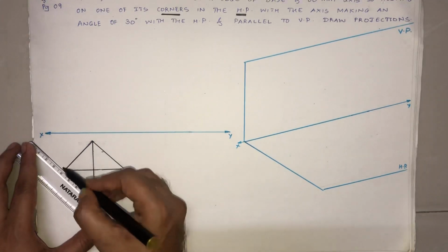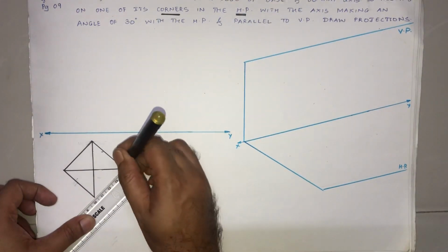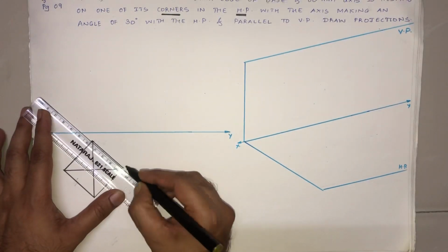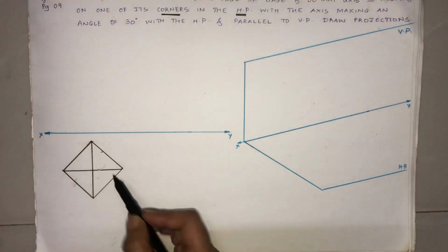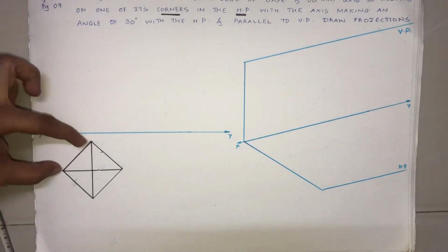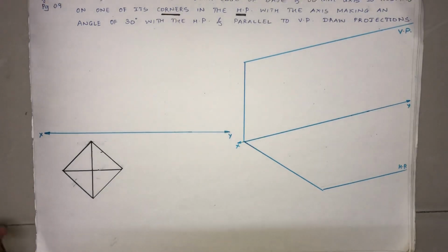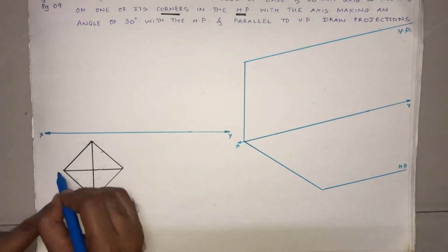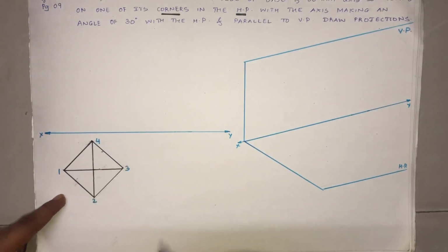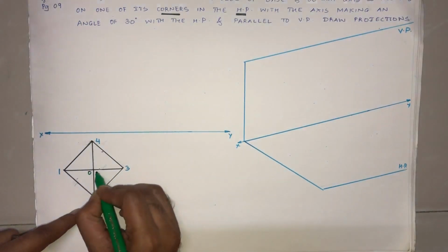So that's the base of the square pyramid. While constructing, what you have to do is take 45 degrees. You have to draw these lines equal to 40 mm. Then keep your compass, take this in your compass, and from here you draw an arc. From here you draw an arc. So you will have a square. Okay, I'm going to name this in this manner, like this. And this is going to be O M.